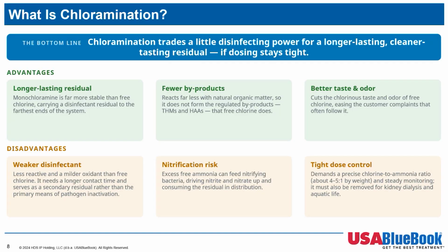If that ratio is left to drift, the leftover ammonia becomes food, which is the whole nitrification story that we'll get to. One practical thing people forget, monochloramine has to be removed before the water reaches dialysis equipment and before it reaches aquatic life of any kind. Fish, amphibians, reptiles, and the invertebrates at the bottom of the food chain are all sensitive to it. And unlike free chlorine, it doesn't just sit out overnight. It has to be actively removed. Worth getting ahead of because these are the calls that will come in.